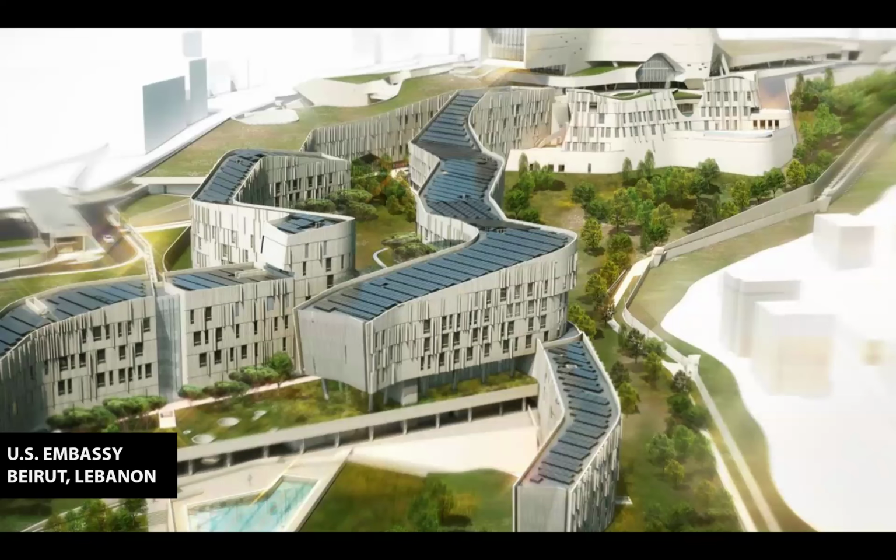They will yellow, they will crack, they will craze if you utilize them for exterior applications. I see it happen on ticket windows all the time just because someone wanted a cheap solution for a ticket or transaction window. Please utilize glass if you truly want a longer life cycle project to go the entire duration of the life cycle of the building. So great question from a sustainability standpoint.